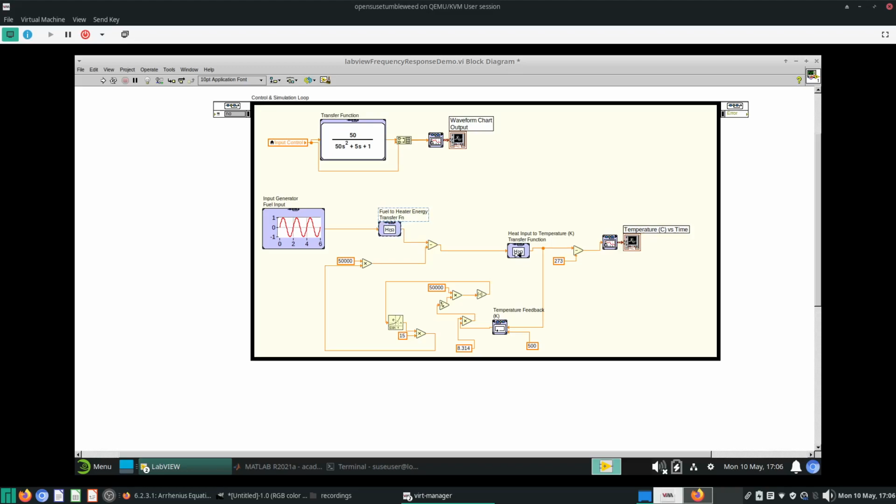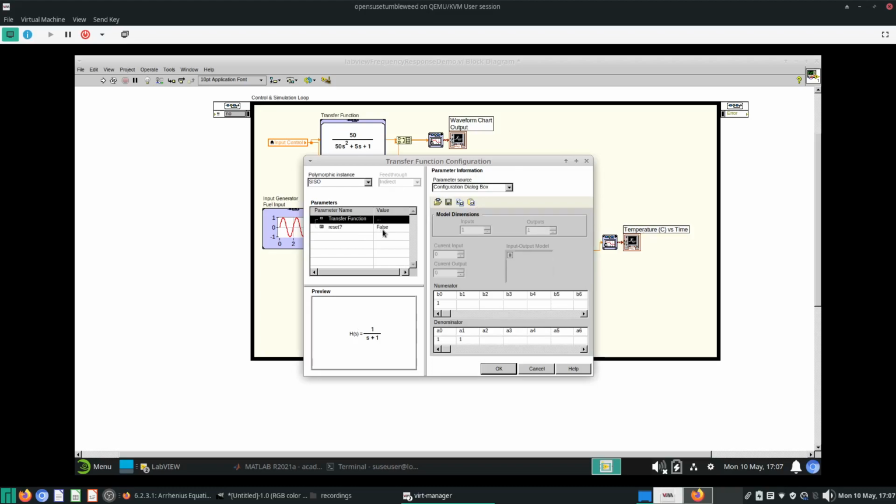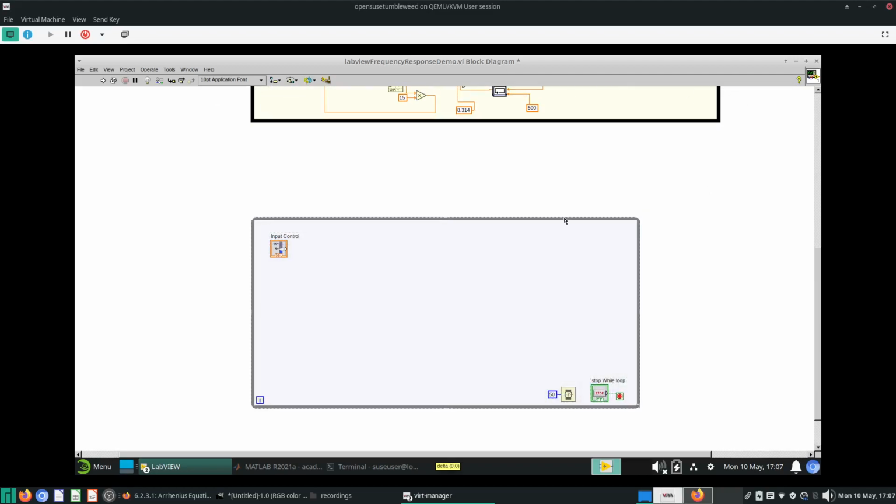Both of these are first order, and I'm not going to do anything that complicated with them. The complicated part is the nonlinear thing, which we might want. Frequency response testing may be useful, it may not, but it'll be interesting to see how things pan out. So I'll put 10 seconds as the process time, 0.01, maybe 0.001 as the gain. Not too bad. All right, so this is the system. We may take a while to tweak it, but let's at least put this to the test and see what happens first.